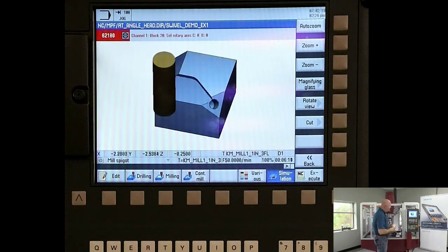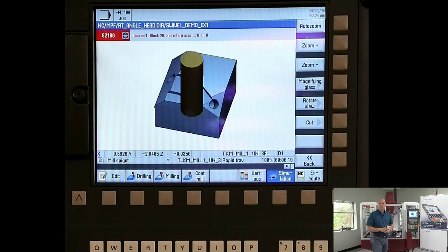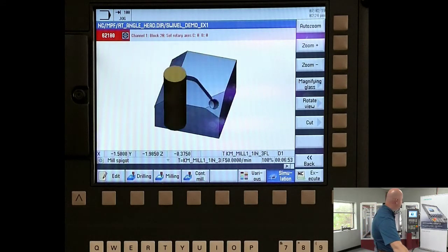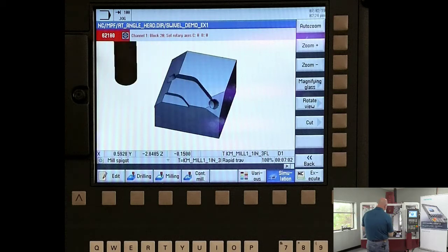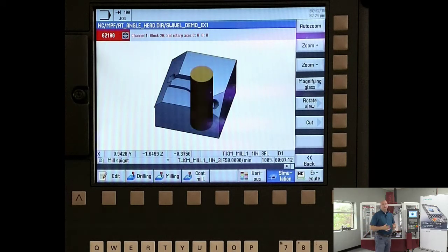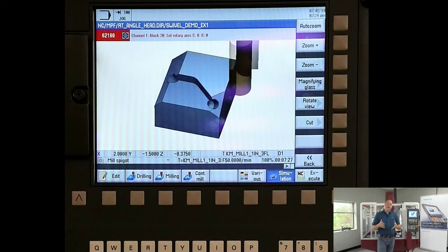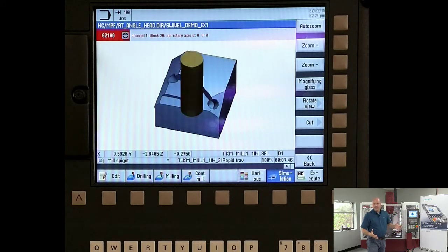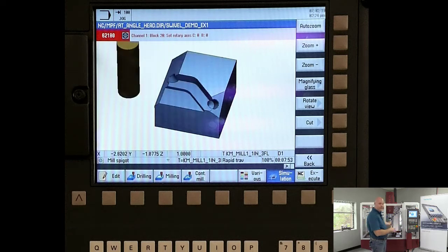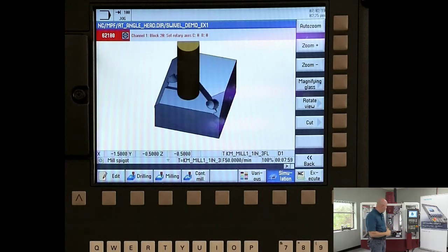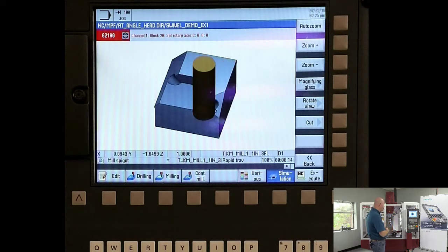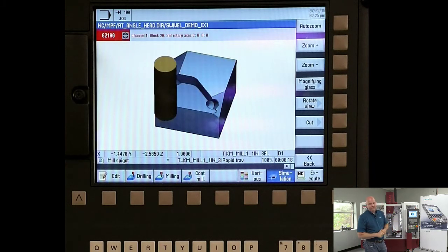This tool itself that's in the spindle is what's called a mill drill. So it allows me to take a side axial load or mill. Basically it's an end mill that's been ground with a 90-degree point. And you're going to find when you utilize tools like this, you're going to get pretty creative in your tooling, because we'd all love to buy 10 of these Big Kaiser heads. But let's face it, these things are a decent investment. So you probably only have a few available to you. So you're going to want to get as much use out of them as you can, for as many operations.